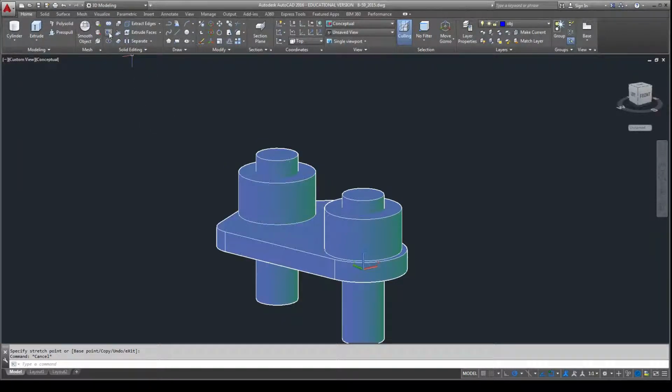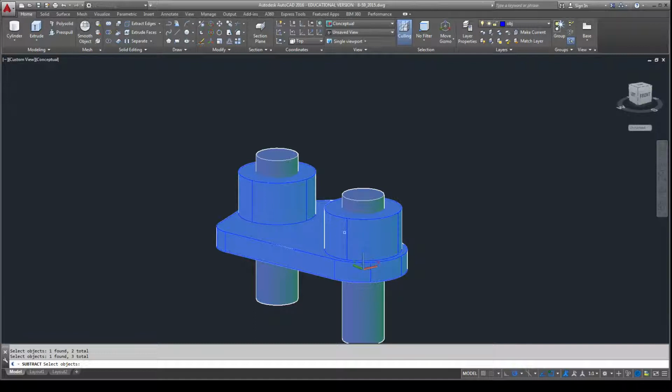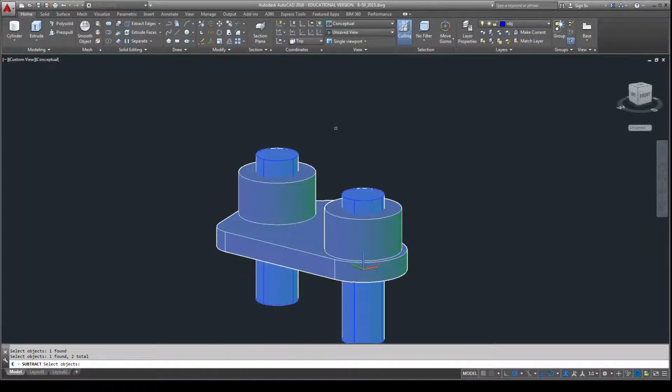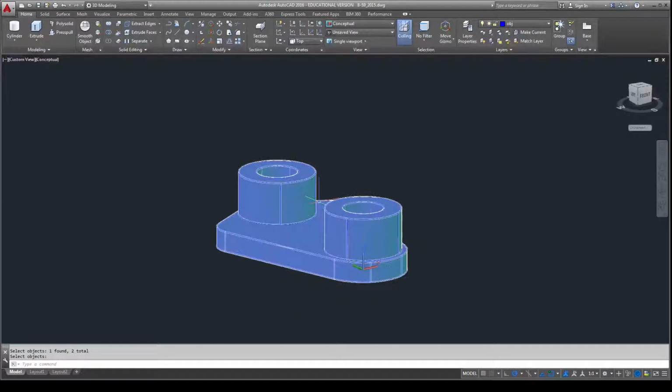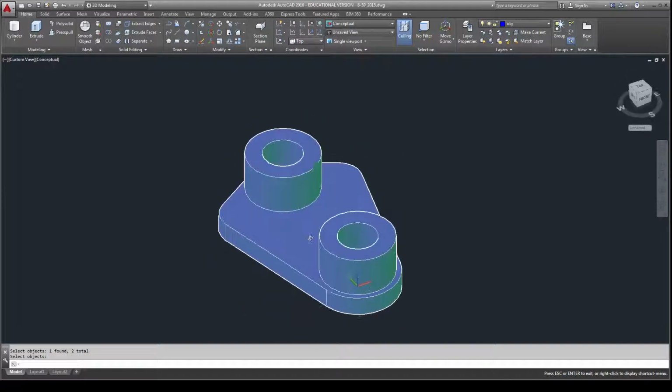And so I'm going to use the intersect, or the solid subtract. I mean, the intersect is a different method, but I'll use the solid subtract, and I'll pick the objects I want to subtract from, which will be the base and the 2 outer cylinders. Space, and then I'll choose the two objects I want to use as the subtracting. At that point, I've cut holes in all three objects. Now there's a hole also, and some slots to create.